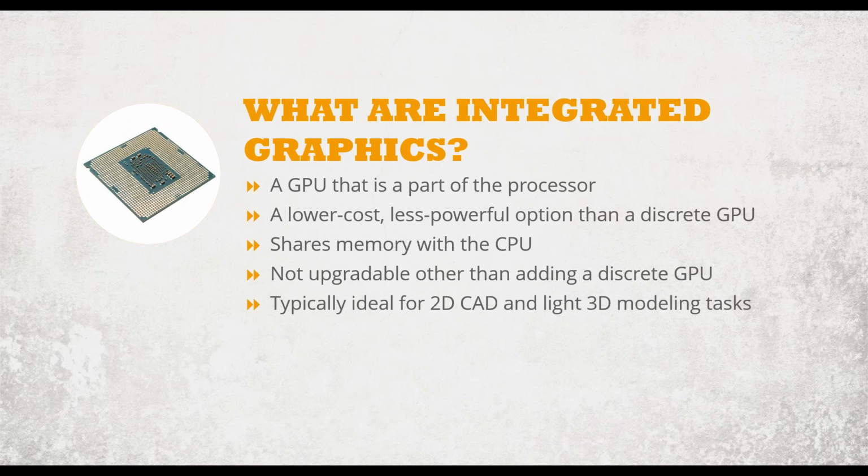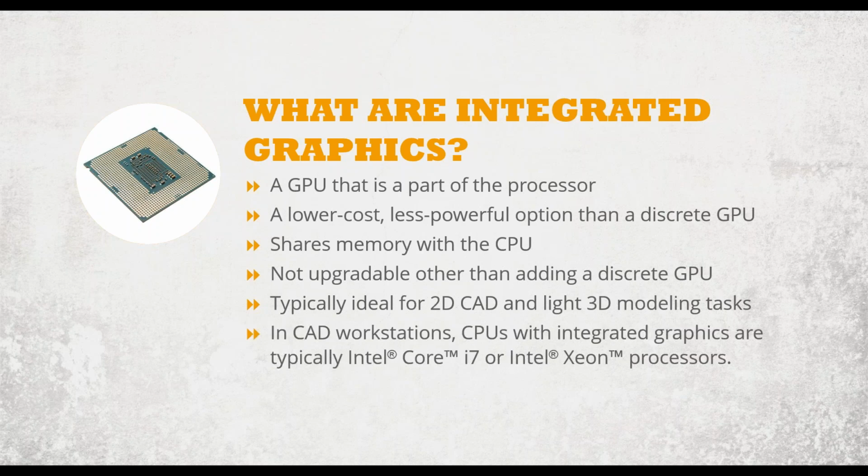So where do integrated graphics work well? Well, they tend to work pretty well for 2D CAD, so this would be something like a MicroStation, AutoCAD, AutoCAD LT, or someone who's doing light-duty 3D modeling, not modeling entire buildings, but modeling certain parts of the building or creating parts in a mechanical CAD application, for example. Not a lot of visualization, not a lot of real-time video going on, just basic CAD work. These are the types of things that integrated graphics can support and support pretty well.